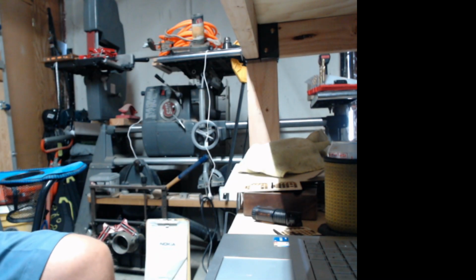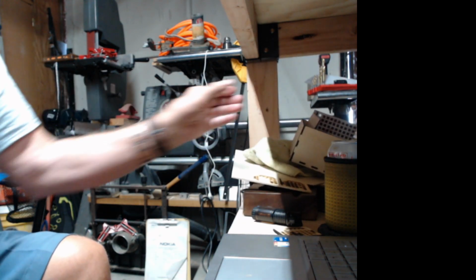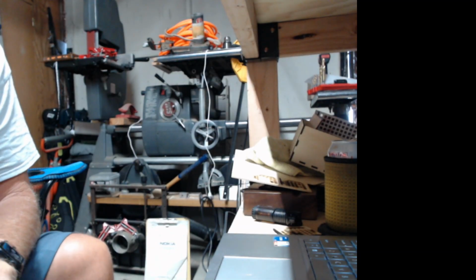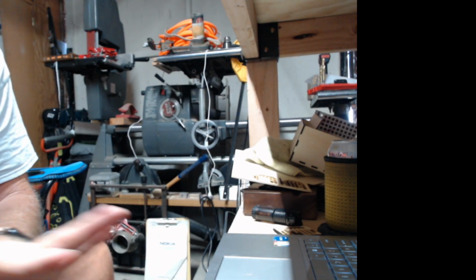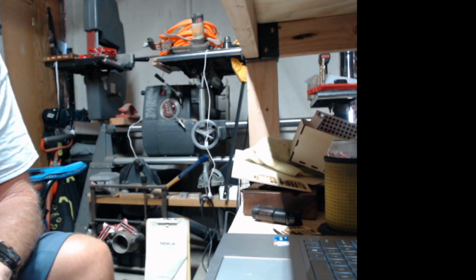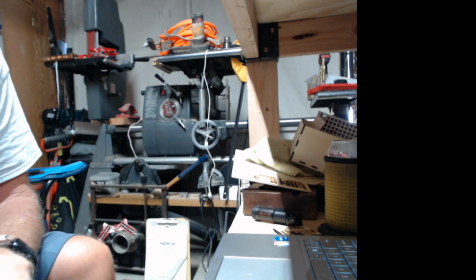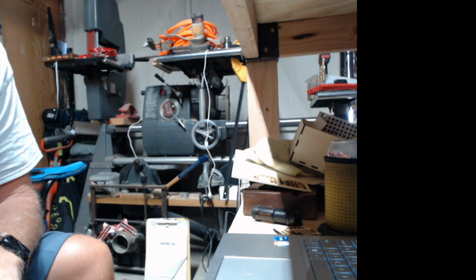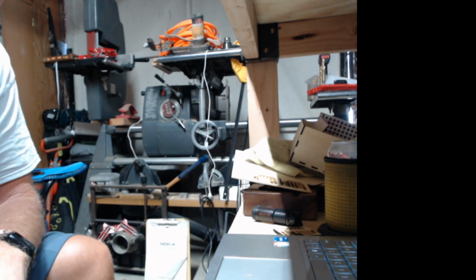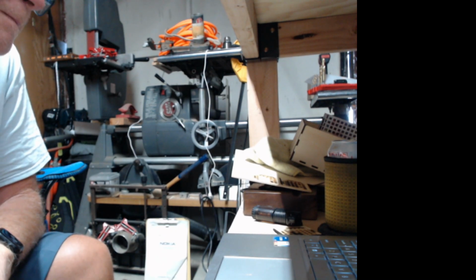So that was it. You do your test patterns, you find out what speeds and settings you need so that you can do these things. Now, cutting is done exactly the same way as what we just did, other than it's not fill, it's lines. And you just change the power levels to levels that you think will cut. I'll save the grid that I just did.